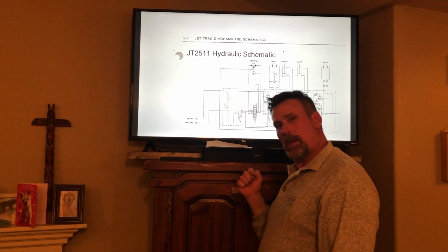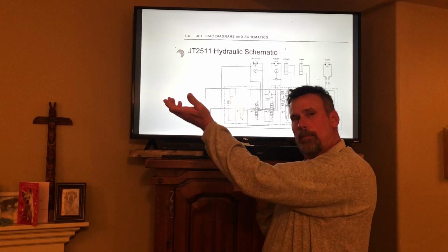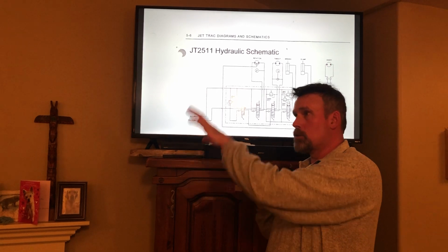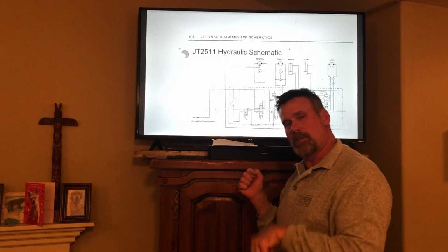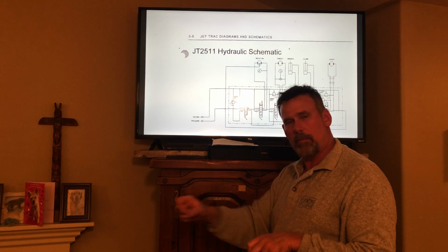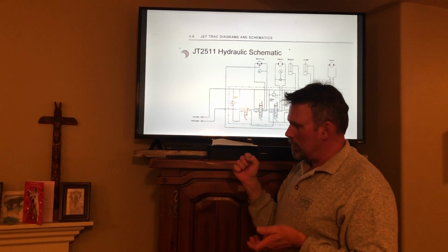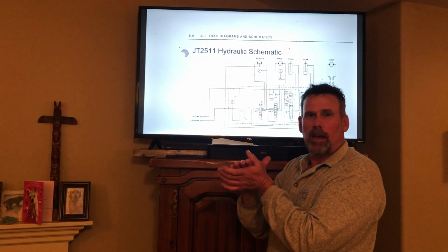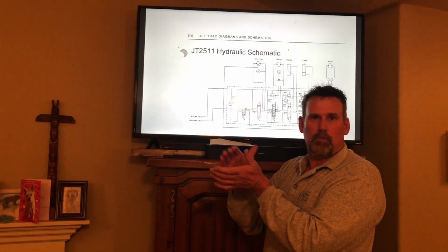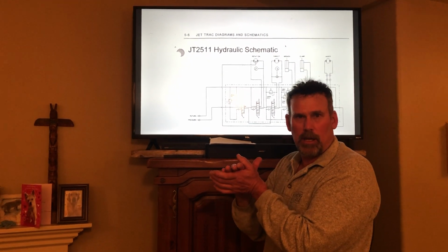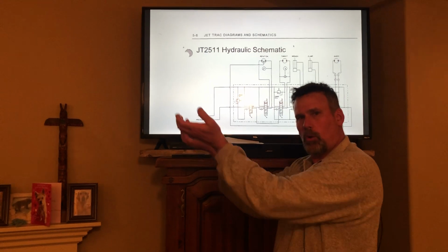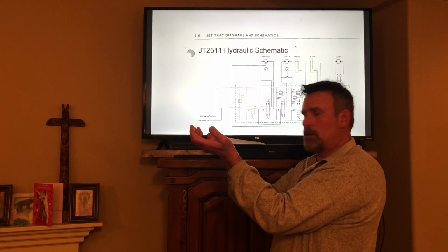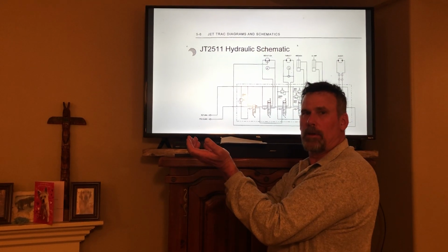So when I pull on the handle to raise that up higher, I have 2,000 psi in the base end of those cylinders, which was holding the gravel up in the air, and I have 0 psi in the main line coming from the pump. So all of a sudden, as soon as I pull that handle, they instantly join, okay, they're connected, and now they meet in the middle, the pressure will drop down to 1,000 psi. And 1,000 psi isn't enough to hold that bucket full of gravel up. So if, once again, slow motion, as soon as I pulled that handle, you would see it drop.